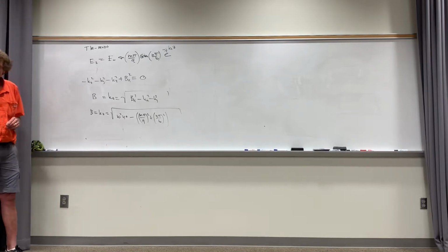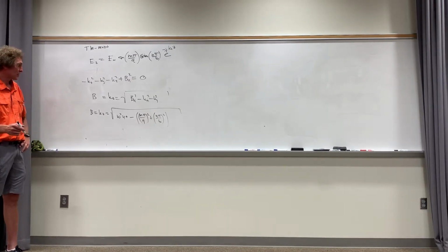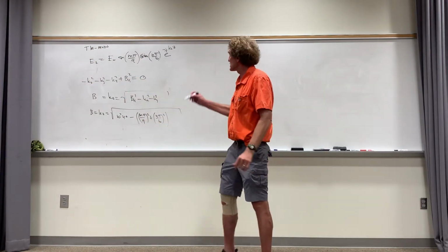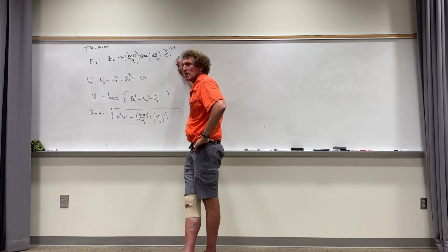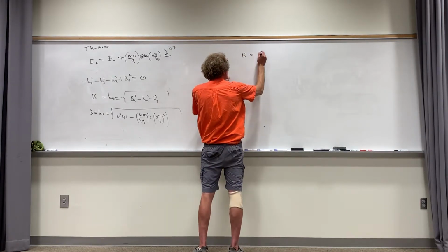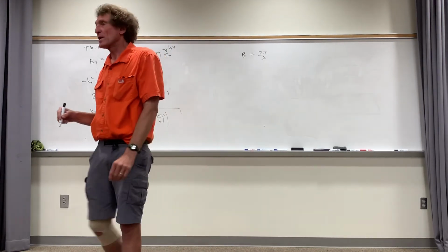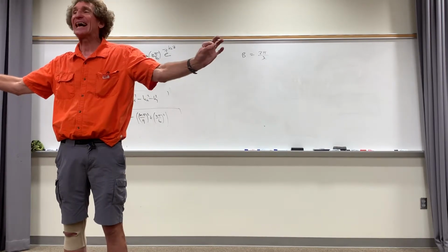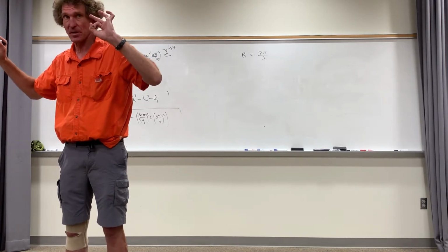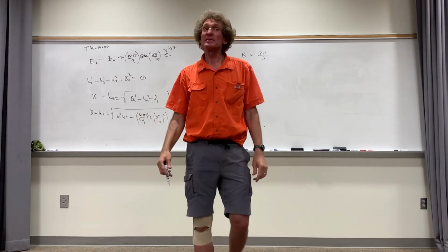All right, watch. This is going to help you. Now follow me on this. Remember this form right here. I want you to look at it for a second. You see where kz is? And I mentioned something called cutoff, didn't I? Now, when you think of beta in general from before, beta was 2 pi over lambda, right? Now, when we're at cutoff, it means the wavelength in the guide goes to infinity, or it means beta goes to 0. All of a sudden, it doesn't propagate. You follow me on that? If this is 0, right here, that means it's got no variation in z, and that means it doesn't propagate.